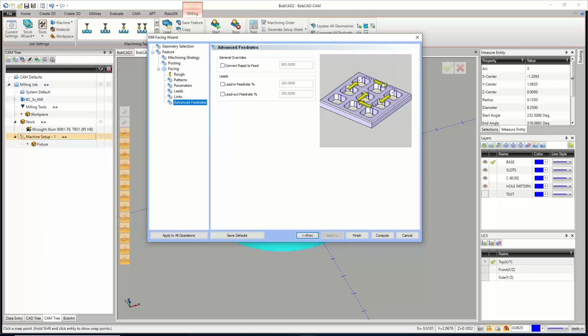A lot of machines do it. A lot of guys don't ever notice it. A lot of it comes down to your fixturing, how you hold your parts. If you don't have anything above your part that you could potentially run into, you don't really notice it. So a lot of the guys that do a lot of the 2-axis work, it's not something they run into super often. But if you ever do see it, it's happening because of the rapid move, because all your axes move at full speed. So essentially what this does is it converts your rapid to feed moves. So it takes the G00s out, adds G01s in, and allows you to define a feed rate that is essentially your rapid, but it ensures that it moves in a straight line and not that zigzag.